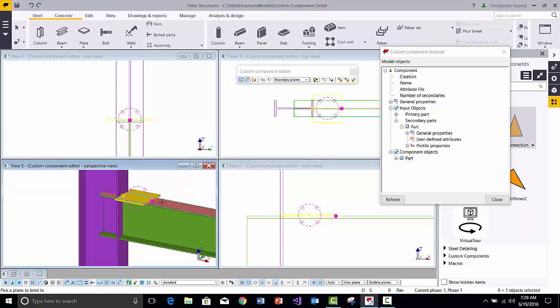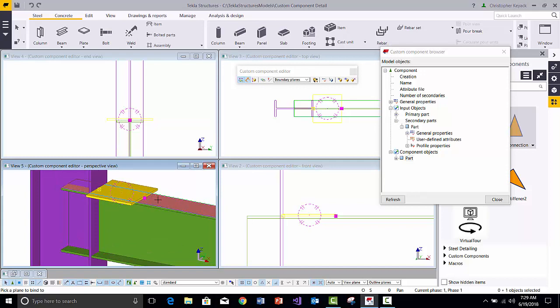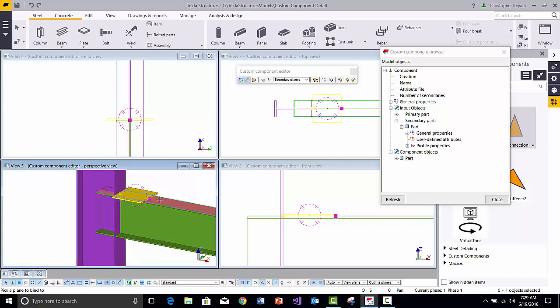So if I've selected this point and I say bind to plane, you'll notice that there's first the boundary planes. Basically around every profile, there's a boundary box. And if you don't really need to get to the specific web or anything like that, then the boundary box is good. Here in this case, we're just going to the top flange, so we're just going to bind it directly to that top flange, and this boundary plane would be fine. If we wanted to bind this, we would just simply click on that plane when it's highlighted, and then a distance or binding would be created.